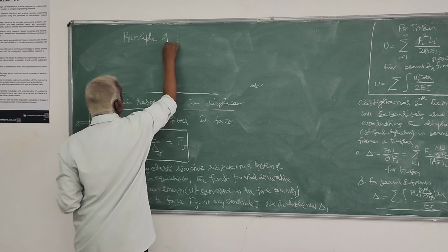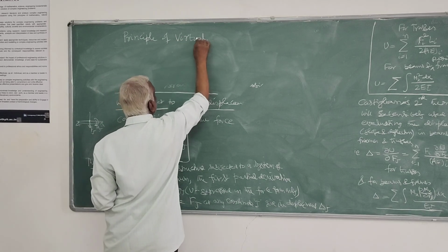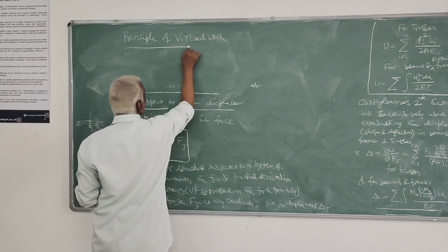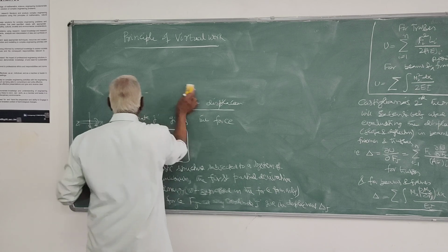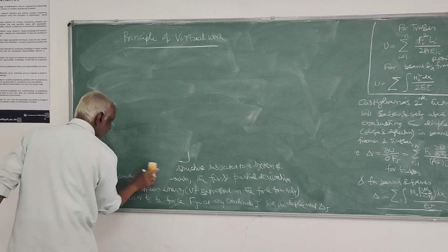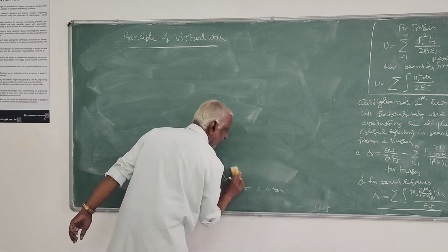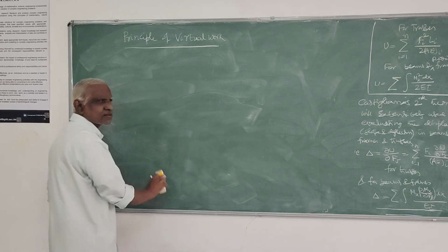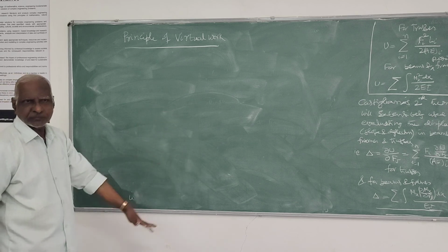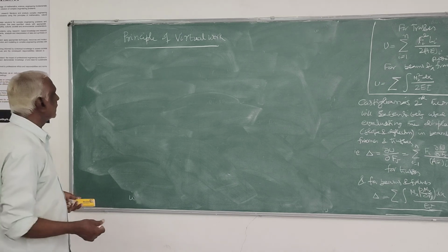System of virtual work. So I spent some time on this principle of virtual work. That principle is used for deriving the expression for the dummy load method of finding the displacement. I'll state the principle and I will straight away give the expression for the dummy load method, which we can straight away use for working problems.